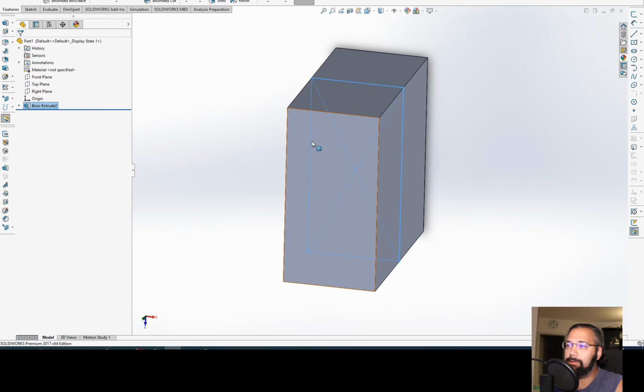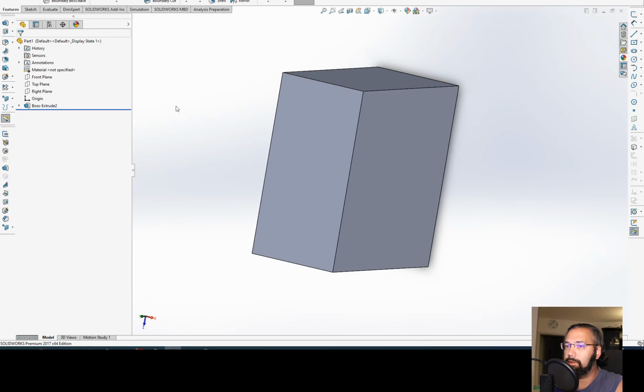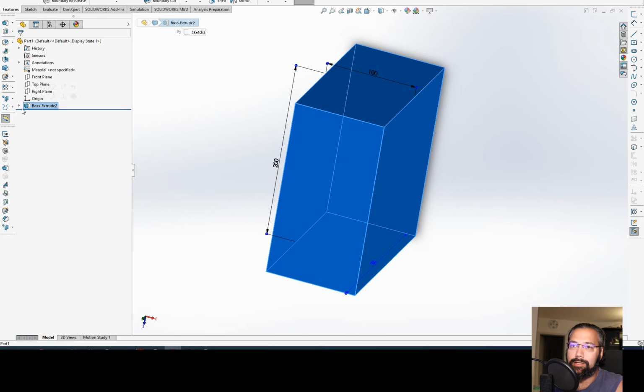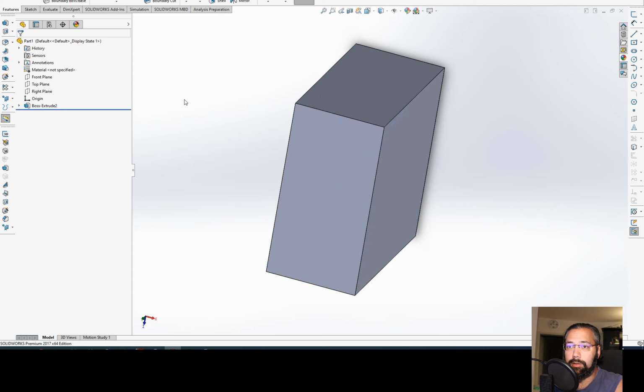Anyway, you click OK, you get your volume. The sketch usually should get eaten by the feature. It still lives there, but it's closed, it's collapsed. You can edit the sketch. You click once, not on the text, because then it goes to edit.